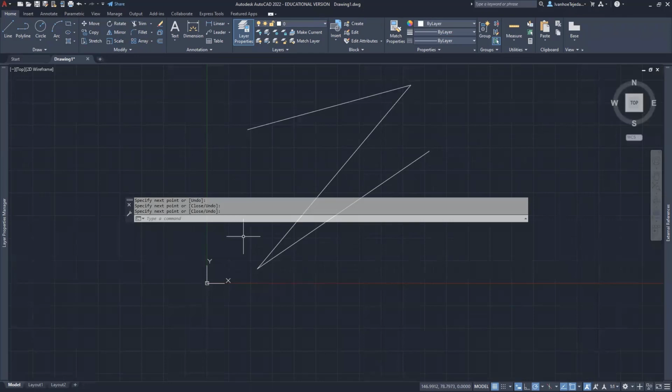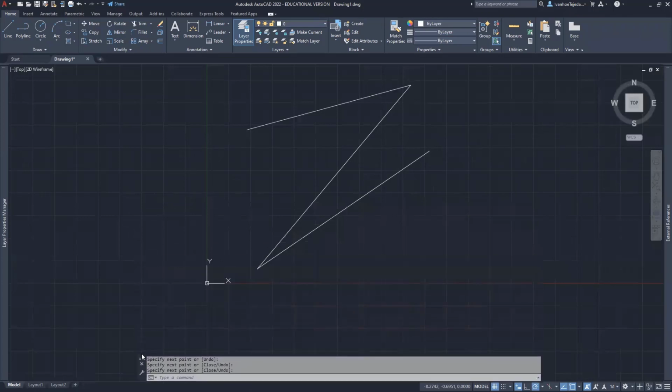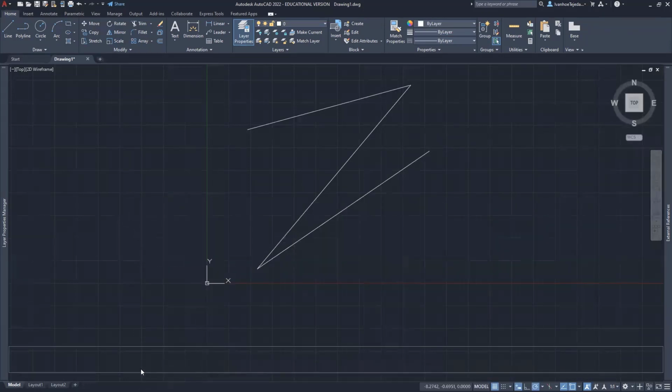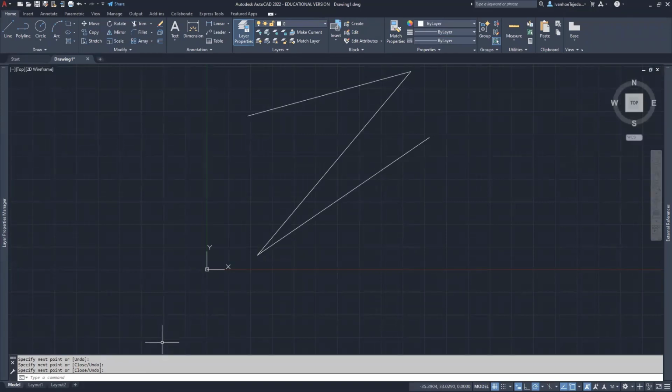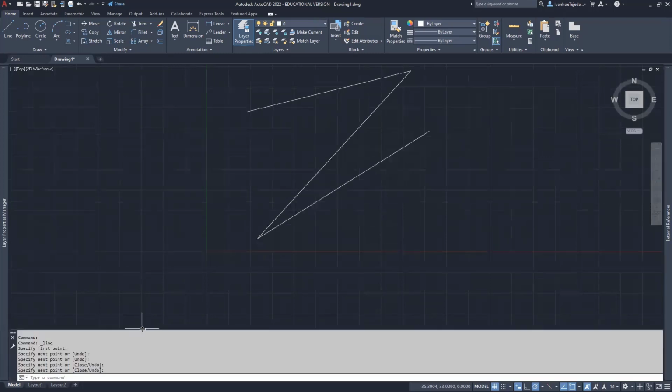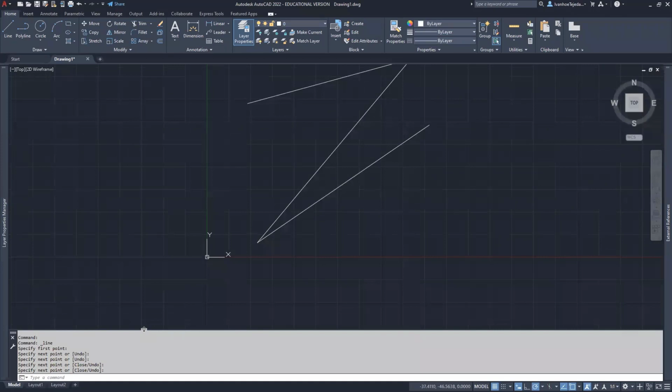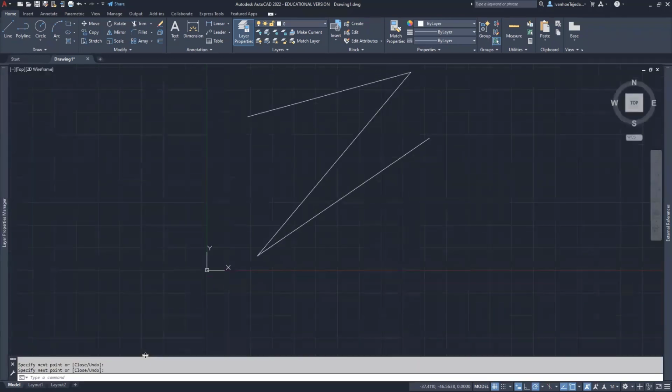Do not close it. In fact, what I'm going to recommend that you do is you take it, move it down to the bottom, and keep clicking down, and as soon as you see it extend to this long ghosted rectangle, release the mouse button. And when you do that, it locks to the bottom of the screen. And then the next thing that I'm going to ask that you do with your interface is hover right here until you get that two-way arrow, so you can make this window bigger. I made mine just a little bit bigger to exaggerate this, but you want to see at least 3 lines of that command line, right? So I have 1, 2, and then the third line here.